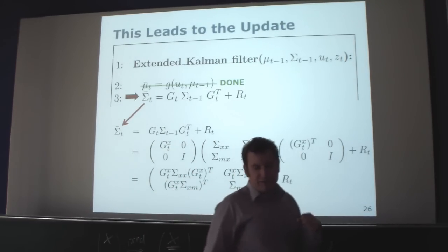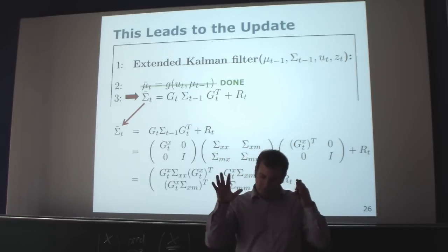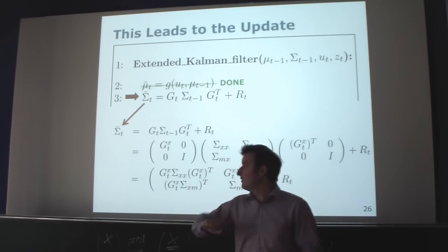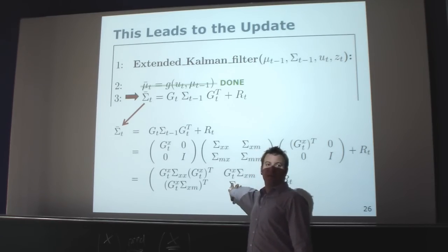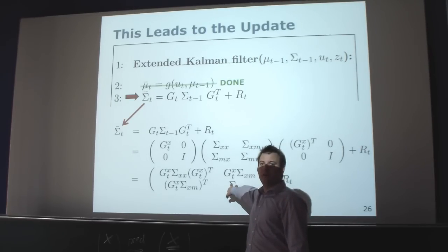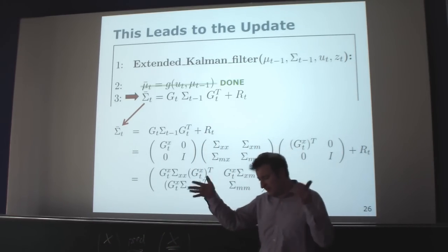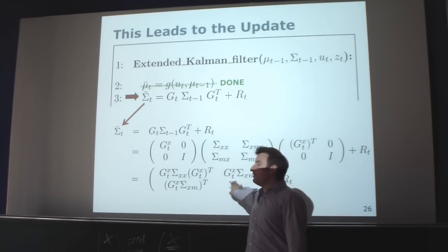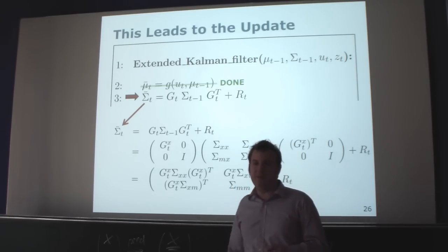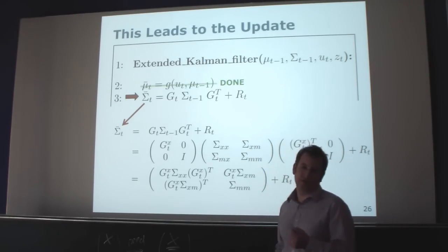So the important thing to note here is that the prediction step can typically be executed quite efficiently in the Kalman filter, because if you look not at the EKF in general, but the EKF in the SLAM case, the reason for this is that this term down here, which we don't change, is actually the big matrix, because it contains all the landmarks. This guy here is just a 3 by 3 matrix, which we can manipulate very quickly. Costly operations are done on this matrix, because this is a 2n by 2n matrix. If I have millions of landmarks, it's maybe a 2 million by 2 million matrix. Therefore, operations on this term are expensive. The others are cheap compared to this block over here. Therefore, the prediction step in the EKF SLAM is something we can typically do efficiently. More costly is the update step, where the whole matrix gets changed.